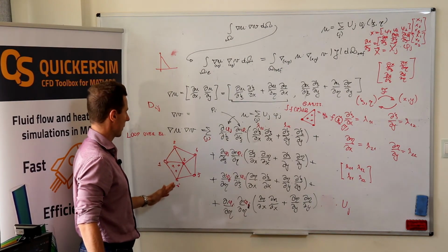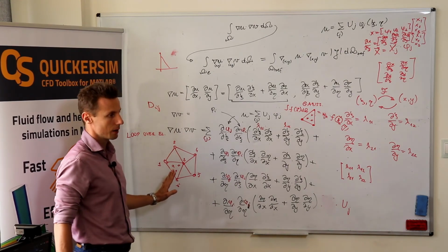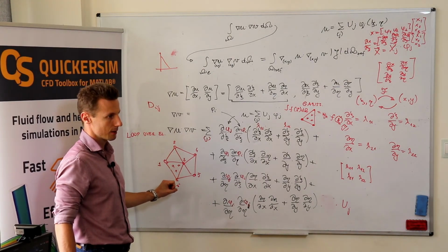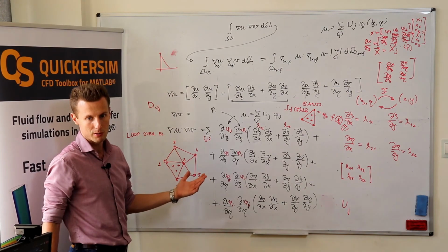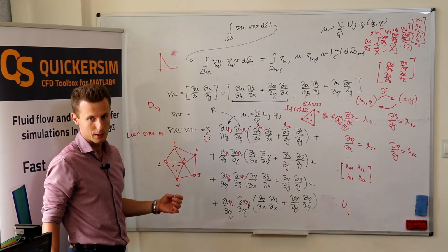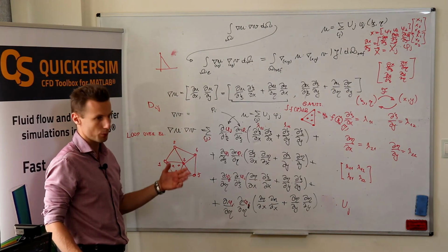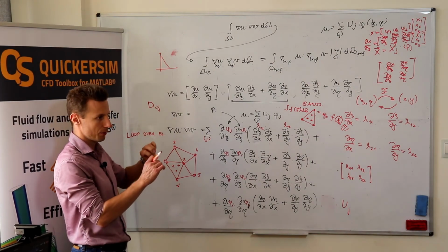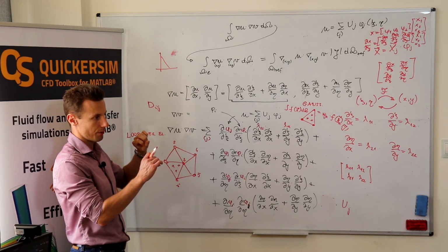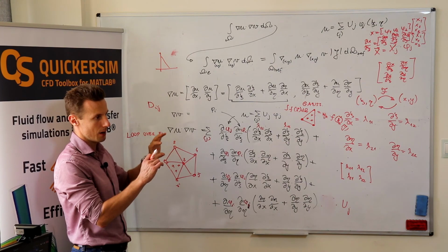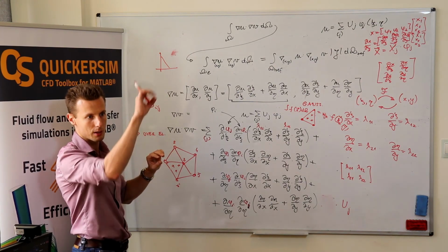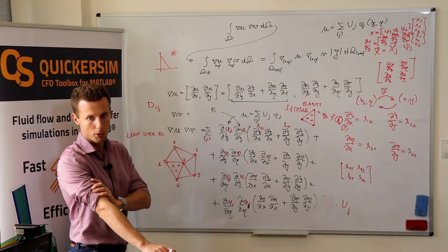Then you come up with the local diffusion matrix, and we repeat the process that we have discussed exactly in our 1D example, where you distribute the entries of the local diffusion matrix to contribute to the global matrix.